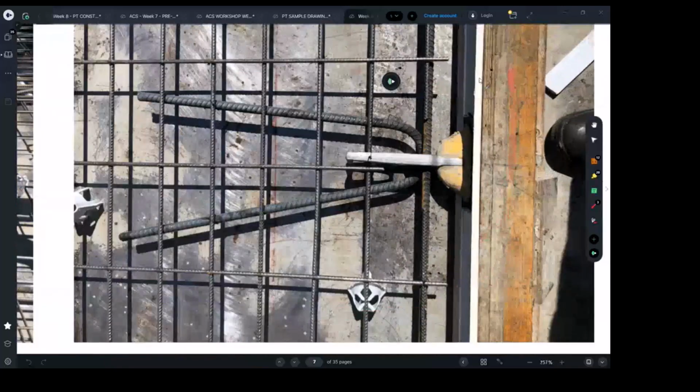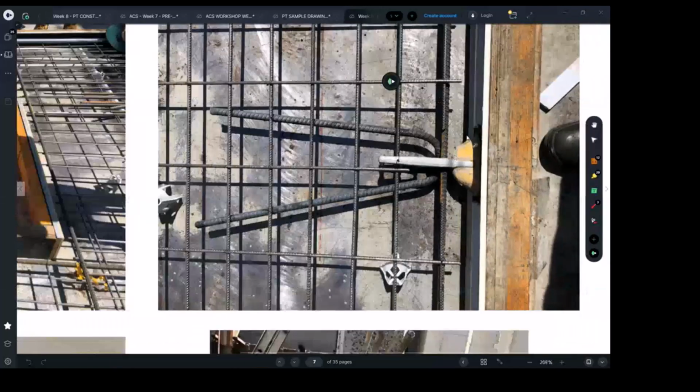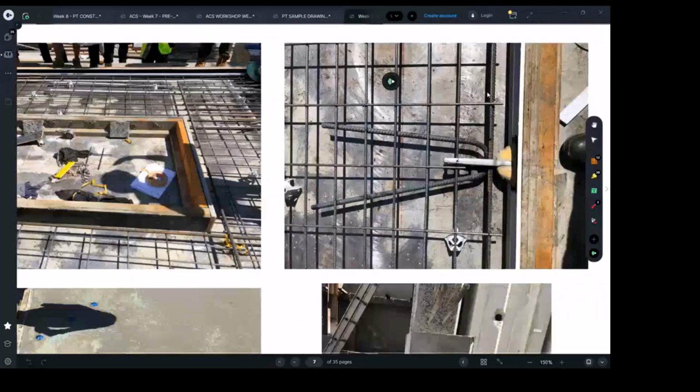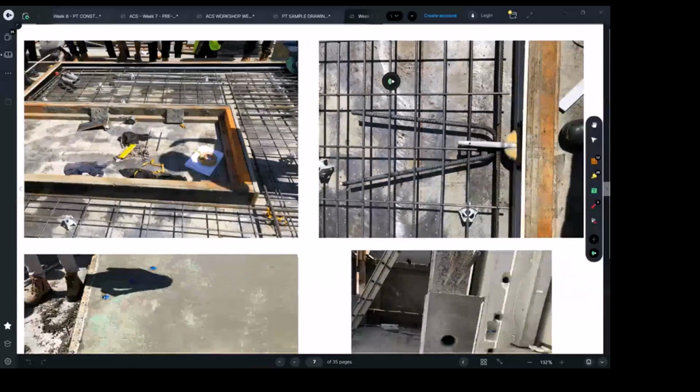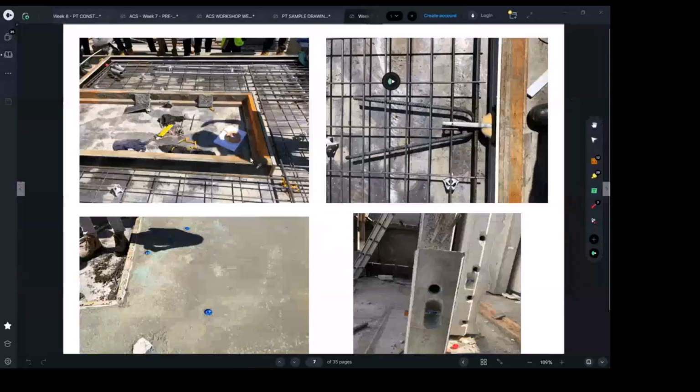This one here. Yes, that's right. So this is basically a single panel which you are building on site. Maybe you're building a warehouse somewhere in the middle of a farm, far away from the city, and it was decided that you're going to be building those precast panels near its final location. Then after they get ready, you can tilt them up to their final location on top of a strip footing.